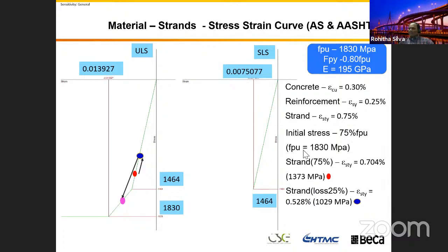Okay, the breaking stress is 130 in this curve. Normally when we produce the pre-stressed concrete section, we stress our concrete element up to 75% initial stress. So you are here in your dot point, 75% of your initial stress, that is 173. So you are in your red point, right?